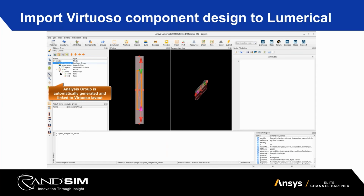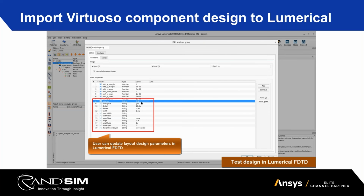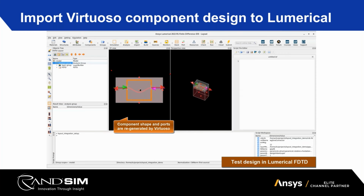When you expand it, you see the layer builder, and you see the simulation region and the ports are automatically added. Since the layout is a P-cell, we can change some of the parameters of the layout. Say, for example, here I change the rotation of the layout, and we see the simulation automatically updated. So from here, you can just run the simulation and get the S parameters of the model.